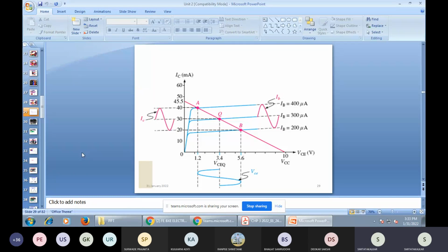And if the transistor goes to reverse bias on the output side, like the emitter and collector terminal, that's why it is operated in reverse bias. And the transistor goes to the active region if the junction of base to emitter is forward biased, and if the collector base junction is reverse biased, then the transistor goes to the active region.